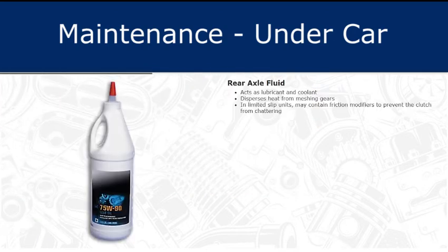Rear axle fluid acts as a lubricant and a coolant. The fluid disperses heat generated from meshing gears while acting as a lubricant. Friction modifiers are used as an additive in limited slip units to prevent chattering.